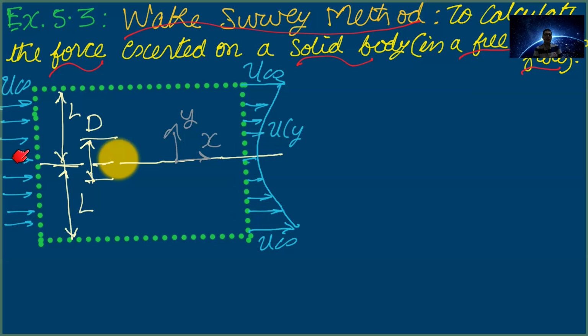Okay, so note that here you are given a constant velocity, here you are given a velocity profile. Note that as compared to the previous problem, in the previous problem you were given a single value of the velocity at the inlet and outlet. Whereas in this problem, you are given a velocity profile. So to calculate the mass flow rate as well as momentum flow rate, note that we don't use an algebraic equation, we use an integral form of equations.